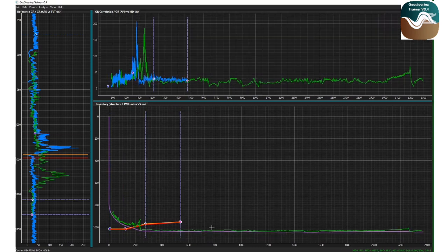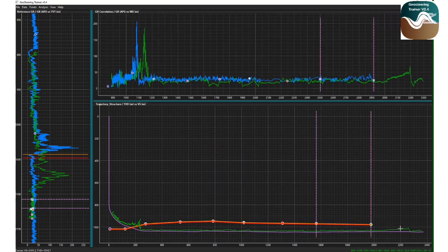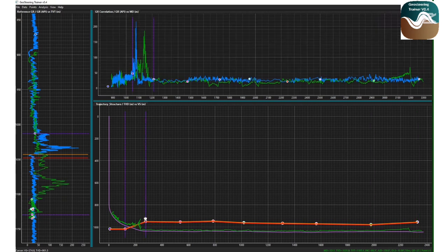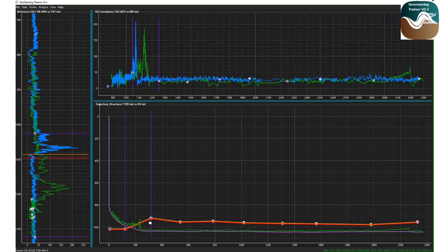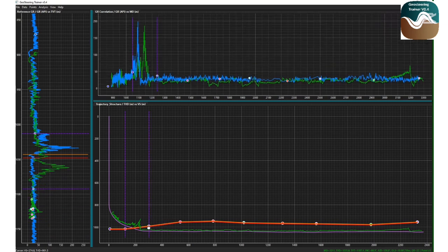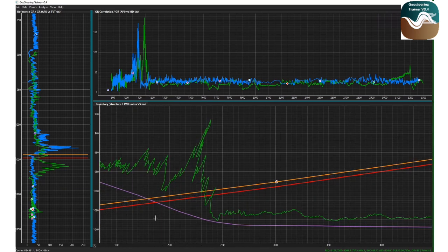The application uses advanced mathematical algorithms to compute the complete 3D trajectory from this survey data. The trajectory calculation engine uses the minimum curvature method with Numba acceleration for fast processing of large datasets. It automatically computes true vertical depth, vertical section, northing, and easting coordinates for each survey point. This comprehensive trajectory model is essential for accurate geological correlation.